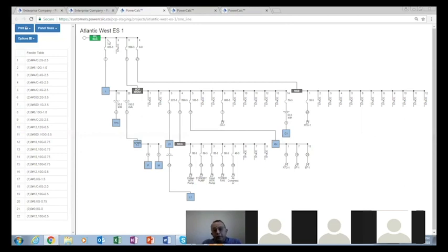Or if you start from the top, you see that circuit number 1 on FPL is connecting panel L. Panel L feeds TP3 and also feeds transformer T1. Transformer T1 feeds a panel named P and a panel named M. All of that happened as we input the circuits in each of the respective panels, and then we make the interconnection, as I'll try to demonstrate with the new panel, but I'm going to go ahead and demonstrate it in here.